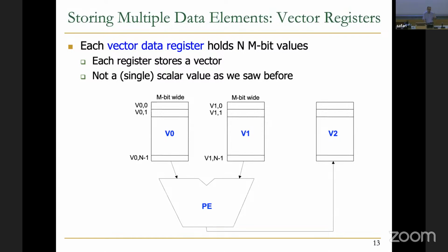Before providing you an example of array and vector processor, I'd like to mention one more thing about this architecture. This is actually important for every SIMD architecture: we need vector data registers. So far you learned about the register file, with registers in SISD architecture that can be 32-bit, for example in MIPS architecture, but they can also be bigger, like 64, 128, 256 bits, and so on. But for vector processor and array processor, we need the vector data register. So your registers in the hardware should be able to store vectors.